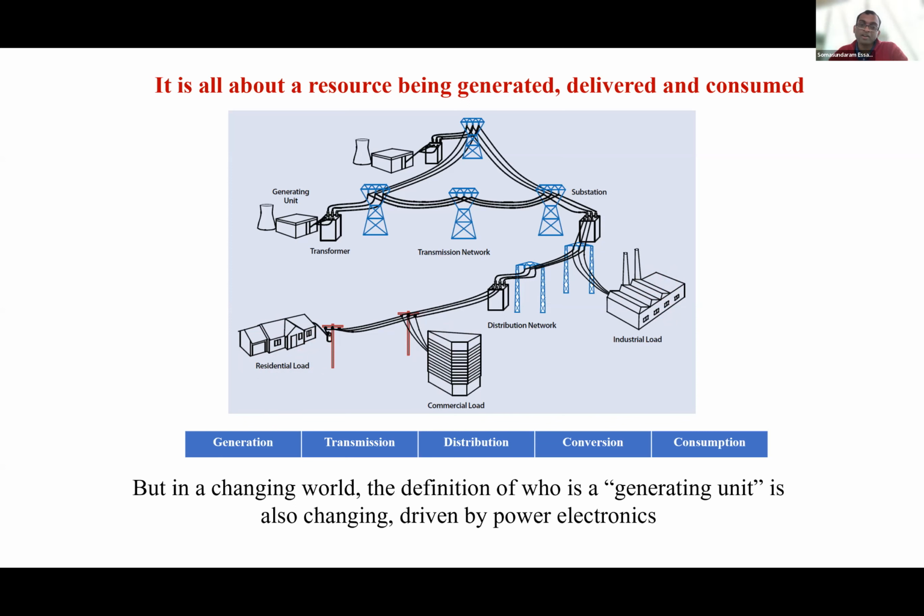Let's say we have a lot of power generation happening there. So the power that is being consumed at these so-called load centers, at least part of it is being generated right there, which means that the stress that the transmission and distribution system experiences goes down, right? And that leads to increased reliability.